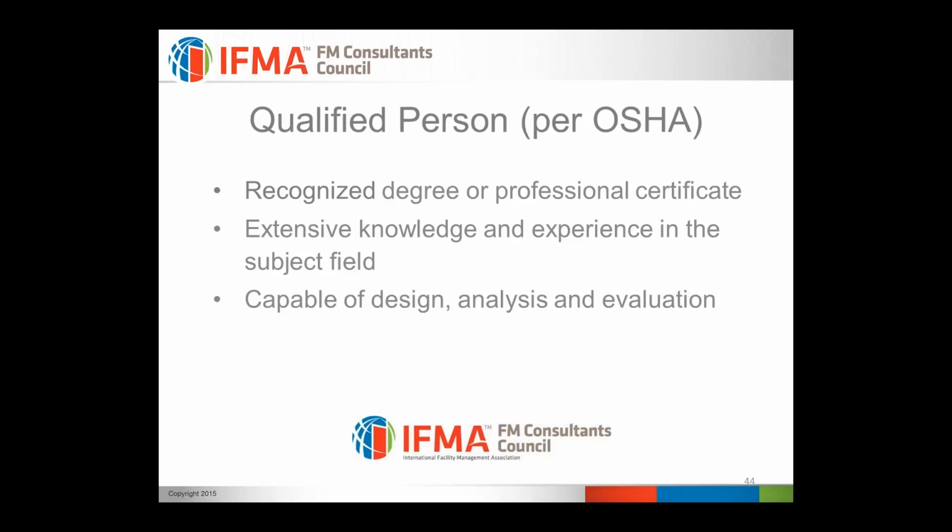And so all of the information that we have, and what I'm talking about right now, comes from the ANSI Z359 fall protection code, and it's referred to as a code, but the ANSI standards are voluntary standards. You don't have to follow them, but it's really recognized as the best practice in fall protection, and certainly when we're talking about certified systems, it's really the only source of information that we have. And so the ANSI standard refers to a certified system as having a qualified person doing the design. And so OSHA does define what a qualified person is, and you can see that on the screen right now.